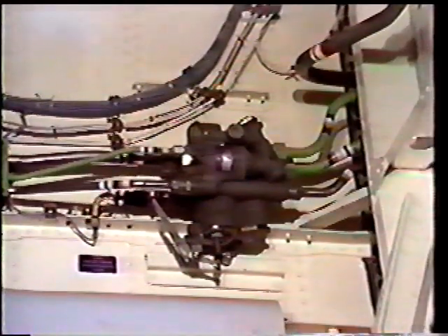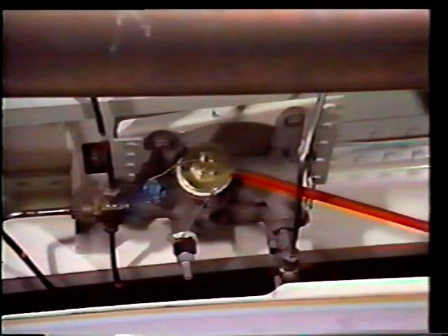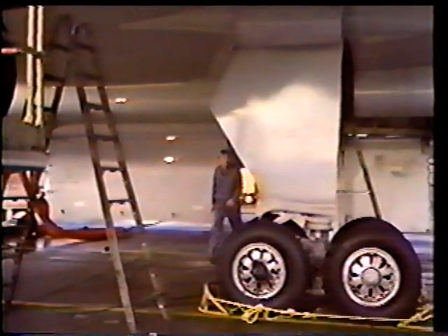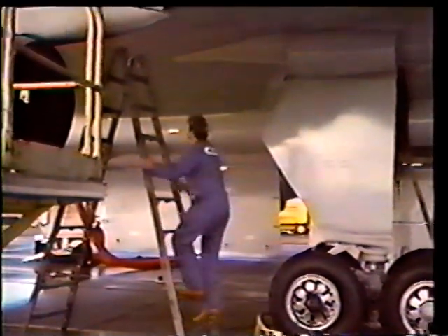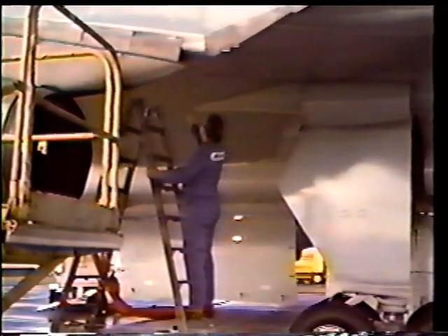The reservoir pressurization module is located on the keel beam forward. Access is provided through either air conditioning door. Its purpose is to pressurize the hydraulic reservoirs with pressure relieved from the left and right airplane environmental control systems. The three hydraulic systems have a fin-type heat exchanger installed in the case drain lines from the EDPs and ACMPs. Left and center heat exchangers are located side by side in the left main fuel tank. Access to the area is provided through this access panel. The right heat exchanger is located in the right main fuel tank and is accessed in a similar manner.